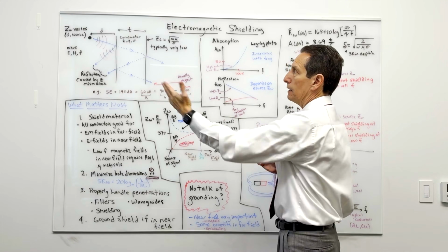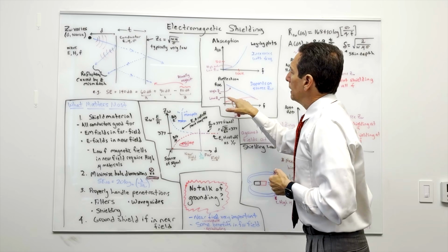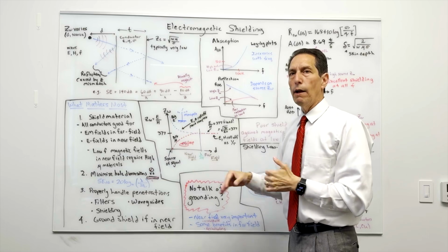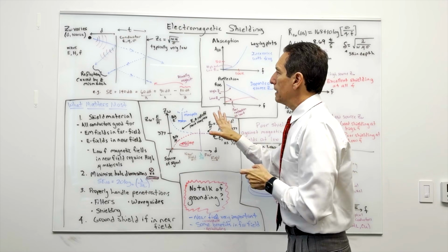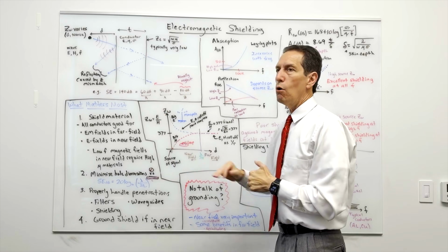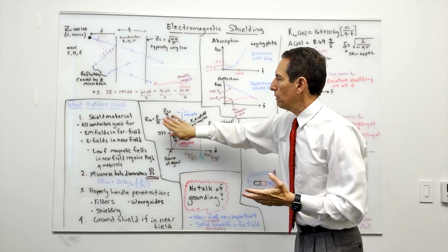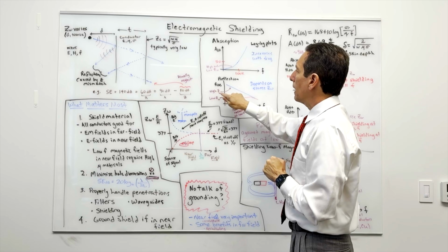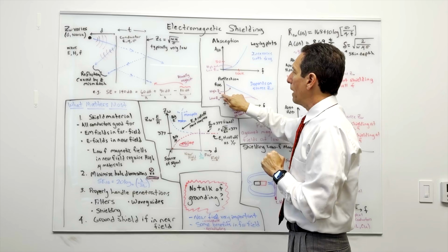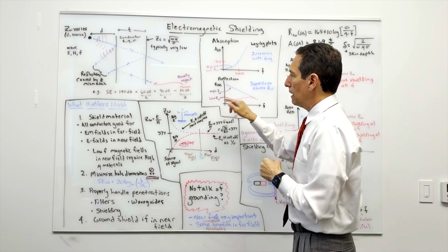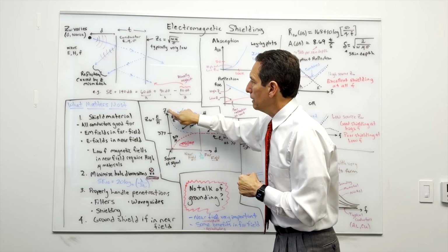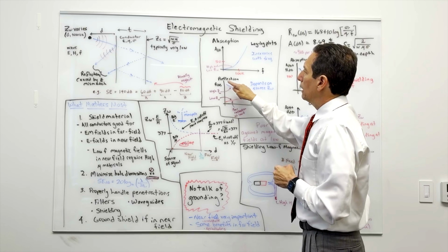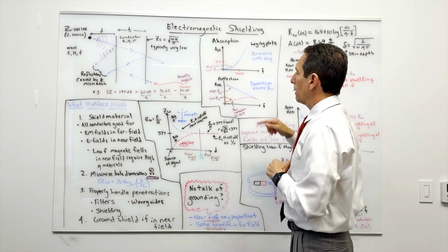Now let's look at reflection. Again, that's the energy bouncing off, right? There are two different curves, okay? And it depends now on the type of antenna that was generating it, and how close you were to it. So again, do we have a low or a high wave impedance? Are we in one of these regions here? If you have a high wave impedance, that might mean we're in this region right here. We have a very high wave impedance, so we have a monopole and we're up close to it. You would follow this curve here, the blue curve.